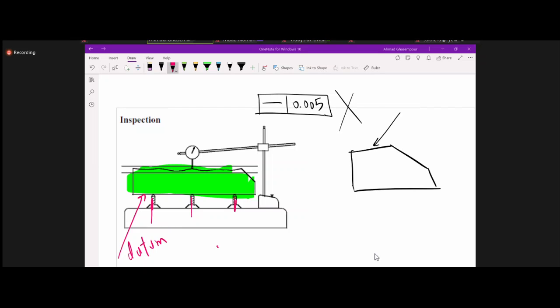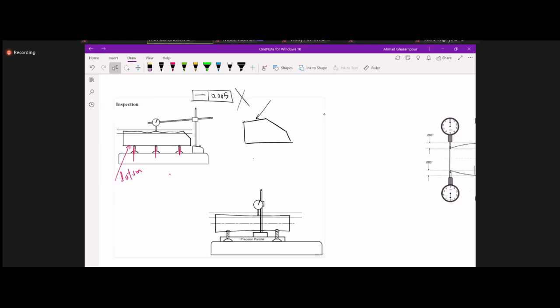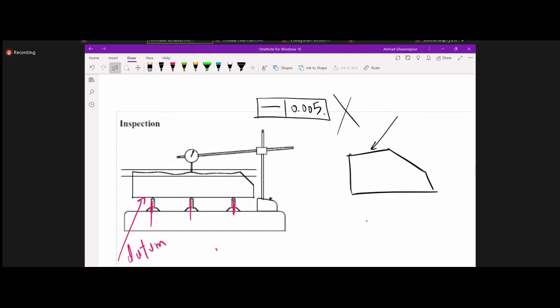So you have to kind of eliminate the effect of the fact that this is setting up on parts. So what you need to do is level the part, right? And leveling this part, these cannot be the same size. So you have to level it so that you get an optimum surface, and that's very time consuming, right? Because you just want to tilt this until you get as flat a surface as possible, and that requires trial and error.